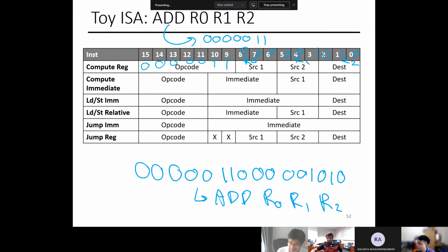Look at the binary, look at the bits, so you know the opcode. Then you know the instruction, so you just do add, multiply, or whatever based on the opcode. At minimum, for the purpose of the lab, make sure you can do the add, subtract, multiply compute operations, the load operation, and the store operation. And for the jump and branch operations, please make sure you try, but I'm going to weight that a little less for your first lab.